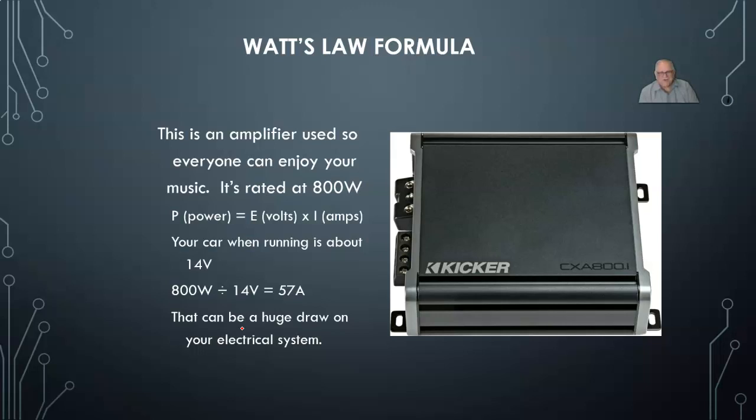However, on amplifiers like this, the only time you're ever going to draw 800 watts is if you have the volume cranked all the way up, and then you hit those bass notes, so everything shakes on the car. That's where it's going to be the high amperage. It's for a short duration, and so the draw on these really isn't that high. It's just surge.